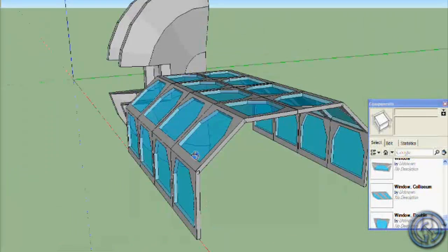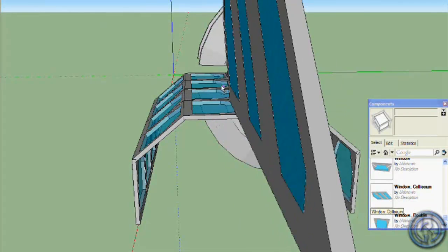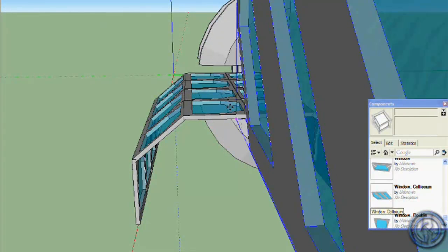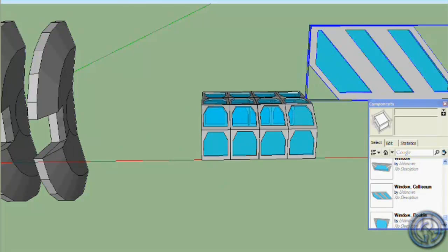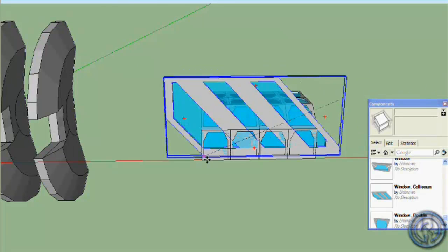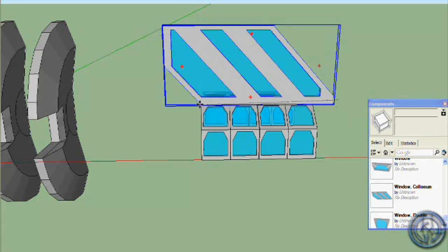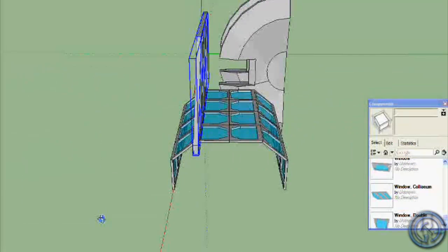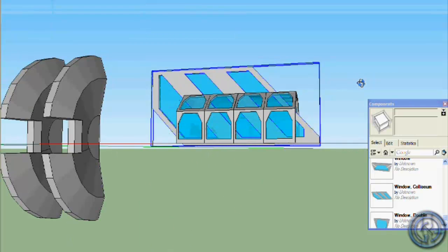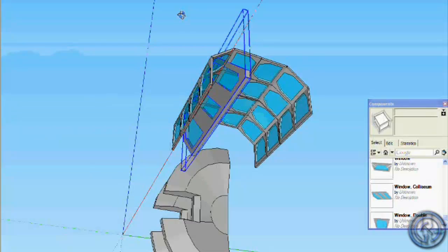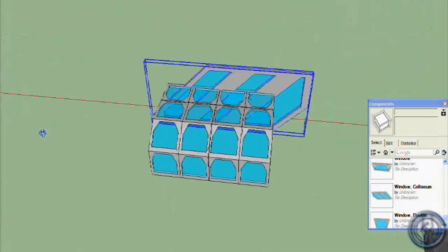I think that's the basics, but now let's do something a little harder: getting objects merged together. As you can see, I have a really big piece right now, and if I wanted to make this go halfway between that, I would try to grab it along the edge there, along the blue axis. You have to grab by the blue axis, or whatever axis you're moving it on, and then just drag towards that side along the axis, and then you have it merged through there.